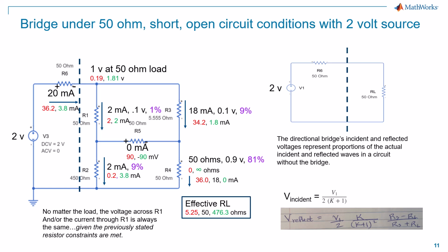And I should also point out, since I'm using terms like incident and reflections or forward and backwards, that this does have a corollary in S parameters. This would be a single port, or S1P type of measurement. Since I've only got an input port, I'm not really measuring anything on an outgoing port. My in and my out is effectively the same port in this case, so an S1P, which allows me to make impedance measurements effectively.